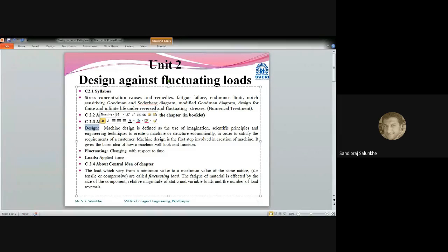So it is changing with respect to time. That type of load we are not going to call a fluctuating load. It is a gradually increasing load. Fluctuating means it is coming back to where it has been started, okay, and may change its direction also. It may become reverse. The reverse meaning is that when we have a tensile load, it may become compressive with respect to time.